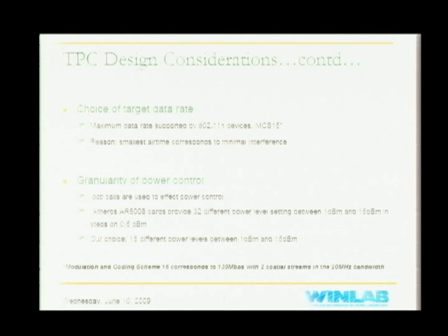When you say rate, what is this rate? This is the PHY data rate. 130 Mbps is based on the modulation coding scheme and a corresponding error correction code. So if the forward error correction scheme needs more redundancy, then 130 megabit per second will stay the same, but the data rate. No, that is for a code rate of 5/6. This number corresponds to 64 QAM and 5/6 convolutional code rate. So the coding is not changing. Yeah, it's not changing. If you want to change the code, then that will correspond to another modulation coding pair, which will correspond to, say, MCS 14 or some other data rate.